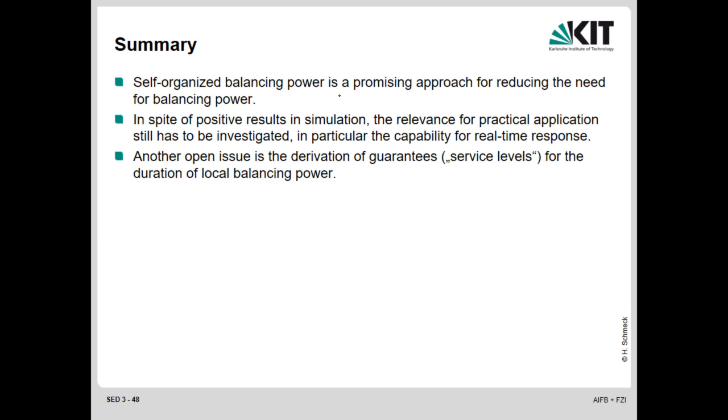So I would say that it is a promising approach for reducing the need for balancing power, and we have seen that this is a source of extra cost in the energy system. If the day-ahead predictions are incorrect, and they are always incorrect to some extent, we always have some deviations during the day. We certainly have the intraday market to even that out, and then we have the balancing power, and the best thing certainly is to reduce the need for extra balancing power. And this can be done by such a decentralized scheme.